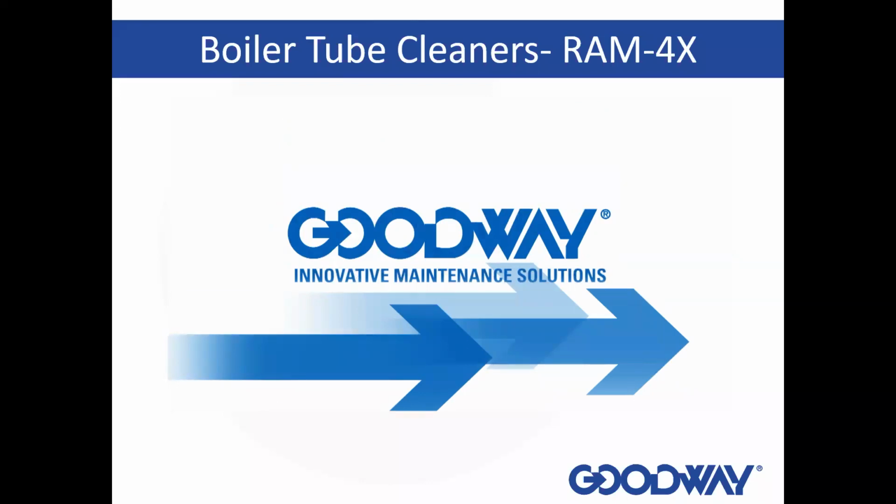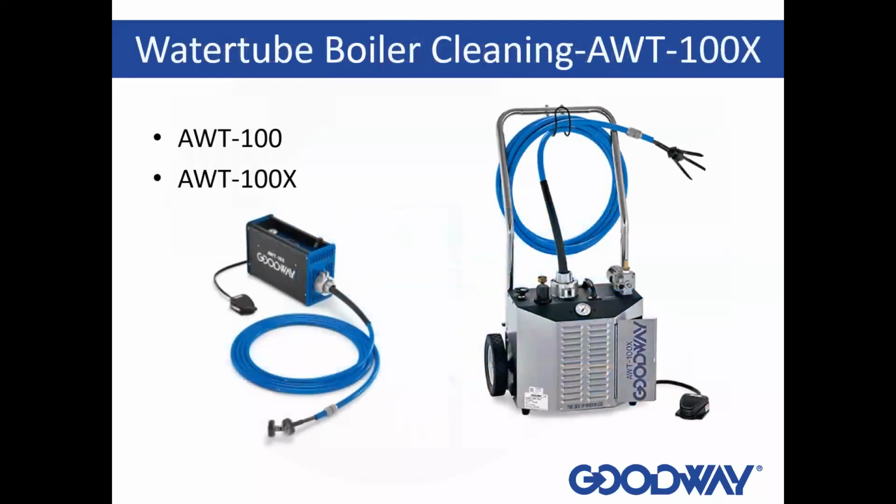Now, that machine was electric. What we've also got are air-powered machines, and they can be used for either wet or dry applications. One of the reasons that we made the smaller AWT 100, that one that's on the left, is it's small enough that you can actually climb into a water tube boiler drum with it and have it next to you so you can clean.